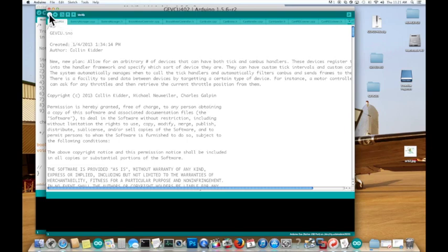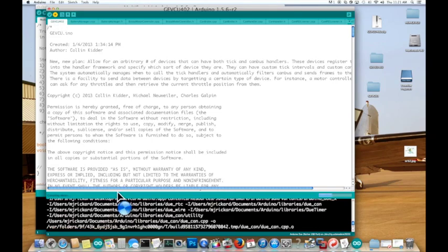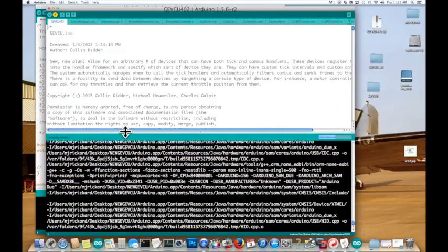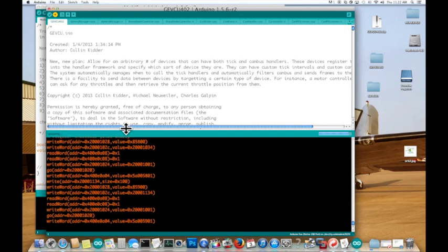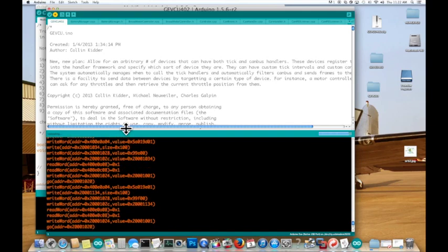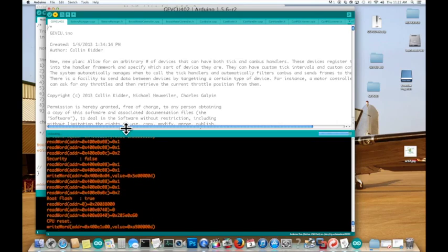This is a verify. It simply does a compile but doesn't upload it, this check mark. The right arrow is upload, but it actually does compile the software when it uploads. And we're going to click that. And you'll see this window down here, which we can even expand if you'd like to see. This is what's going on behind the machine in your PC to compile the various modules of the JEVCU software. And it's a little bit of a process, sort of indecipherable things here.